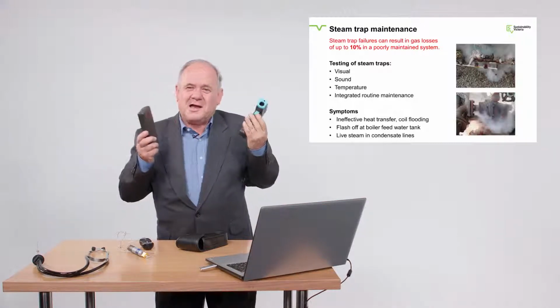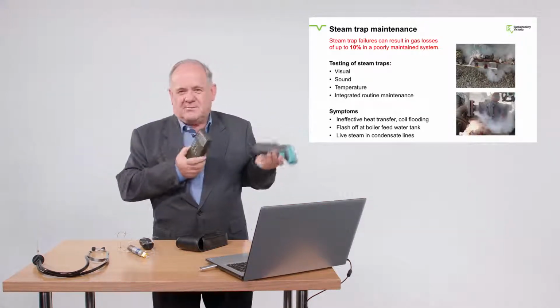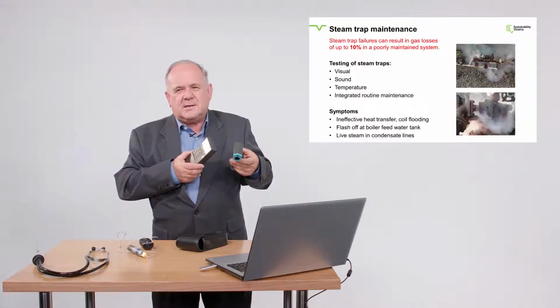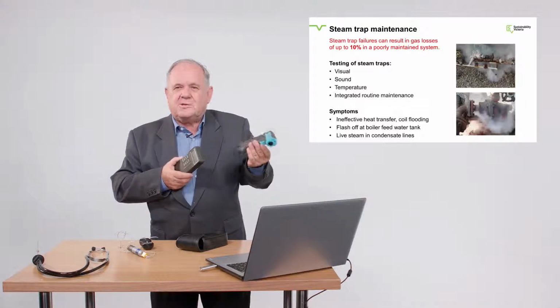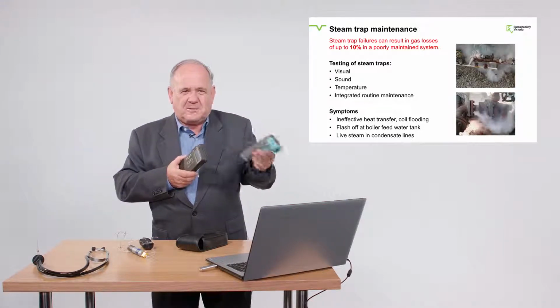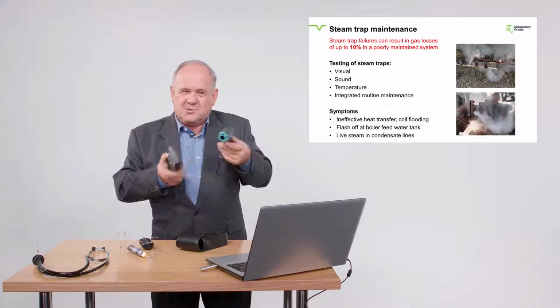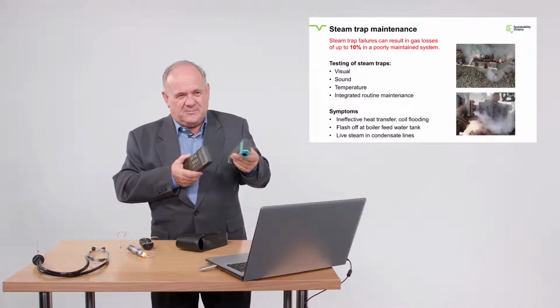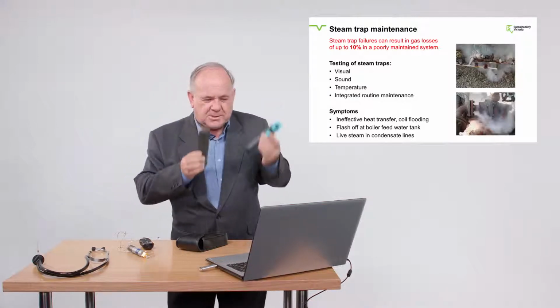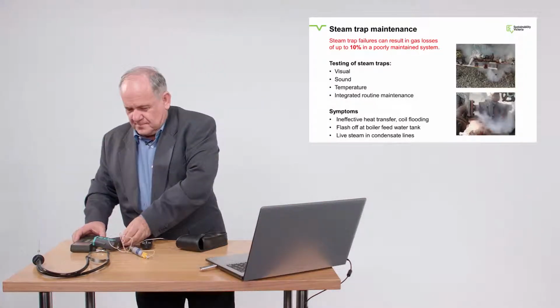So you're not talking large amounts of capital to set yourself up a little kit to measure temperature difference. And if your maintenance guys do it every year, they'll know on that particular trap, what am I expecting? So they'll learn to, once things go different, they'll work out, well, that trap's failed. So that's the temperature method.